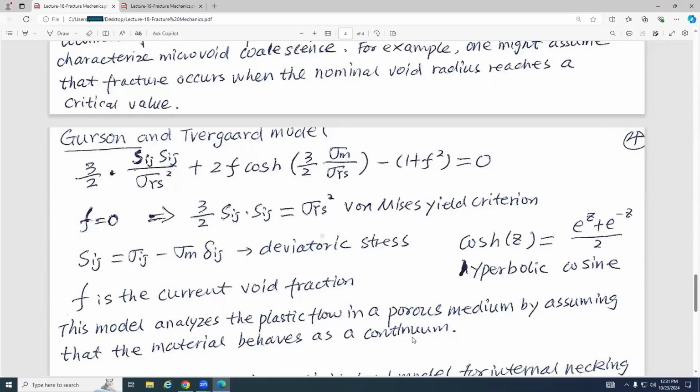As a result, this Sij is the deviatoric stress tensor, and how is the deviatoric stress tensor different from the original stress tensor? The only difference is the three diagonal elements, the three diagonal entries, okay? So you need to use the original one minus sigma m.